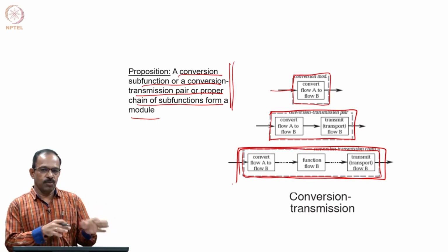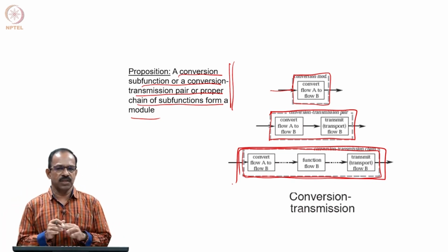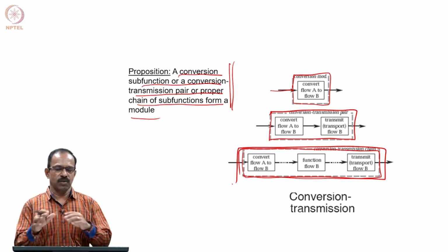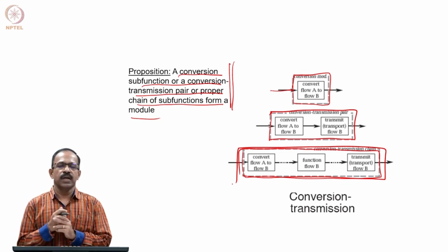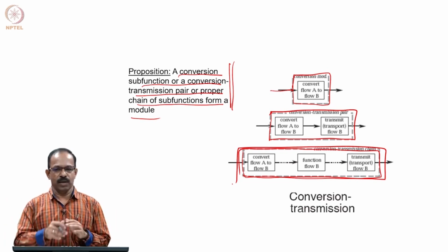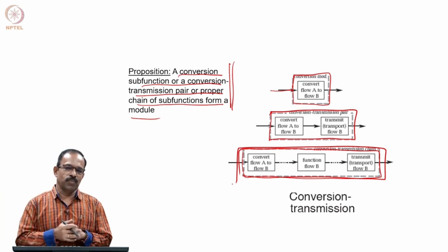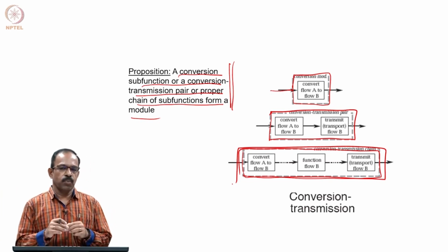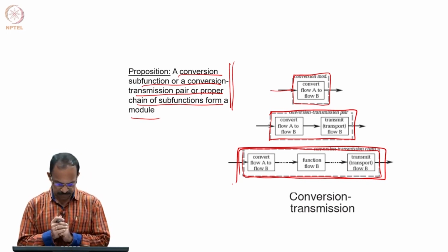And as I told you, there will be a lot of overlaps between the identified modules, and then as designers we need to sit together, identify the overlaps, remove them, and look at the interfaces, and accordingly decide which are the potential modules in the product. Again, that decision depends on many other factors like the number of products you want to introduce and the generation portfolios that you are planning to have. All those things also affect the final decision, but potential modules can be identified using these 3 heuristics.